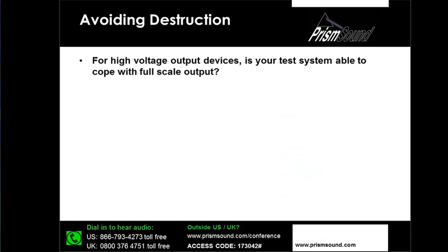And another issue that potentially could cause you problems is amplifiers with very high output voltages. Now, there's a range of measurement equipment out there that you could use to test your amplifiers with. It will inevitably have some upper limit on the maximum voltage that it can safely handle. In the case of the D-Scope Series 3 system that we're using today for our practical demonstrations, it can handle a maximum input voltage of 159 volts.